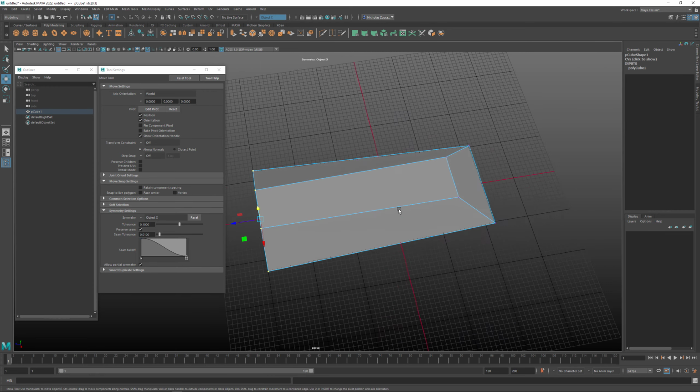And I can turn on this display subdivision so you can kind of see behind the scenes what's really going on here. So if we go back to display level 0, and that's kind of programming terms. In programming terms, they start with the number 0. So this is the base, and then one division up from this, they're going to take each one of these faces. It's going to be divided into 4, and it does a smoothing kind of algorithm between this surface and